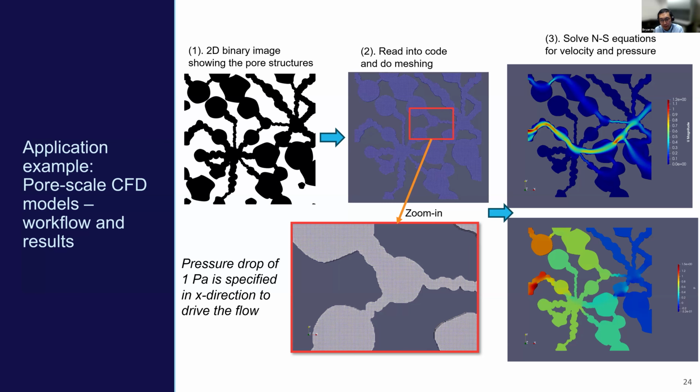So what is left is basically the pressure term and the diffusion term on the right-hand side. That basically reduces the whole Navier-Stokes equation to the diffusion equation essentially. So it is representing the diffusion in a numerical way, just neglecting the inertial terms when doing the computation. I hope that answers your question.